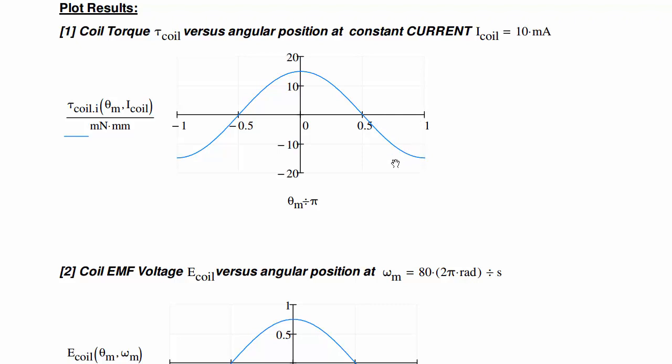If you have another coil in the system, then you could power it during that time. And that's what brushless DC motors do. They have multiple windings, and they power alternate phases at different positions through an entire revolution, so that you are always contributing a positive torque to the motor.